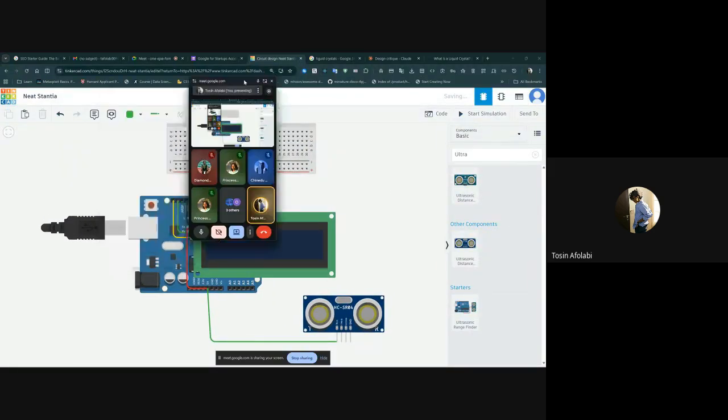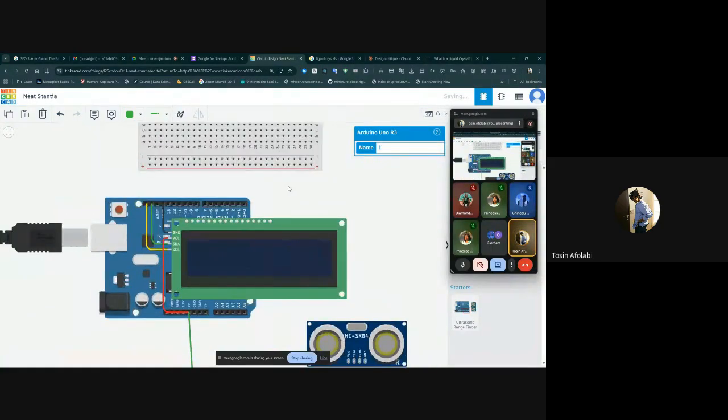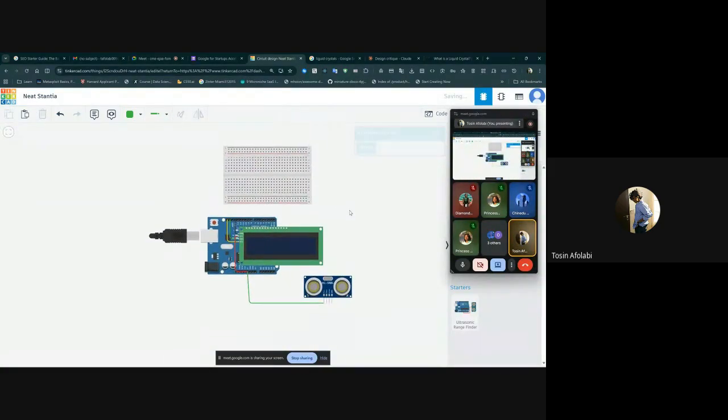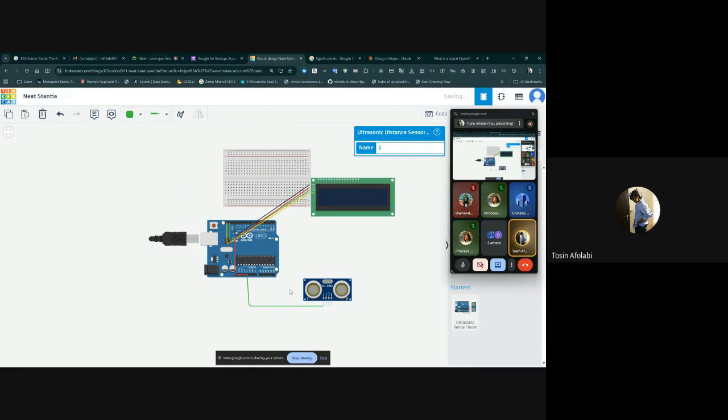for those that want to use the breadboard, I mentioned about putting this Arduino on the left. No, I think it's going to be on the right because of the way the power pins are connected. You put this Arduino on the right, then take this sensor right here and put that on the left. So it's going to be easy for you to wire them, doing any other wiring that you want to connect in the long run. Is that clear?